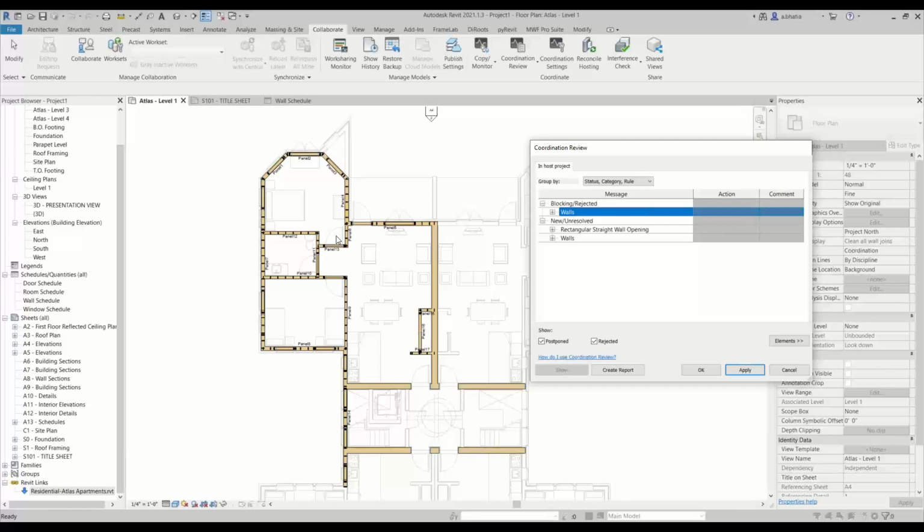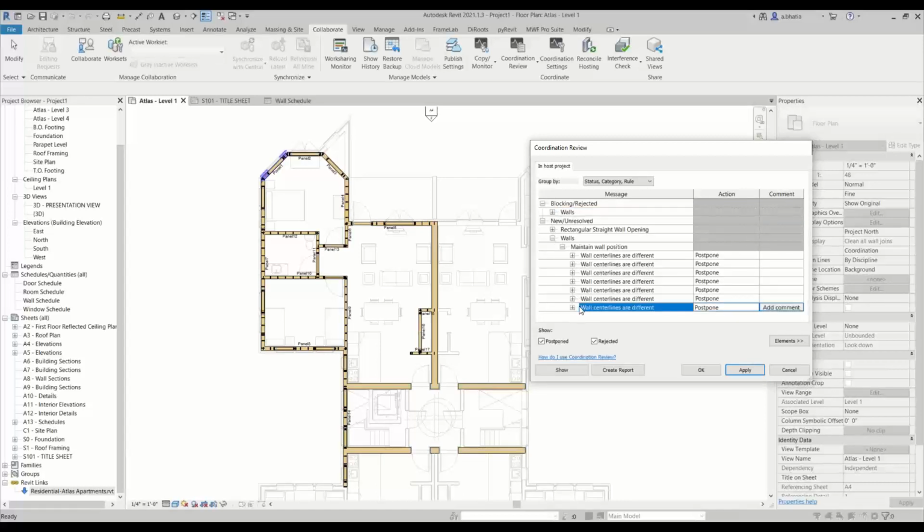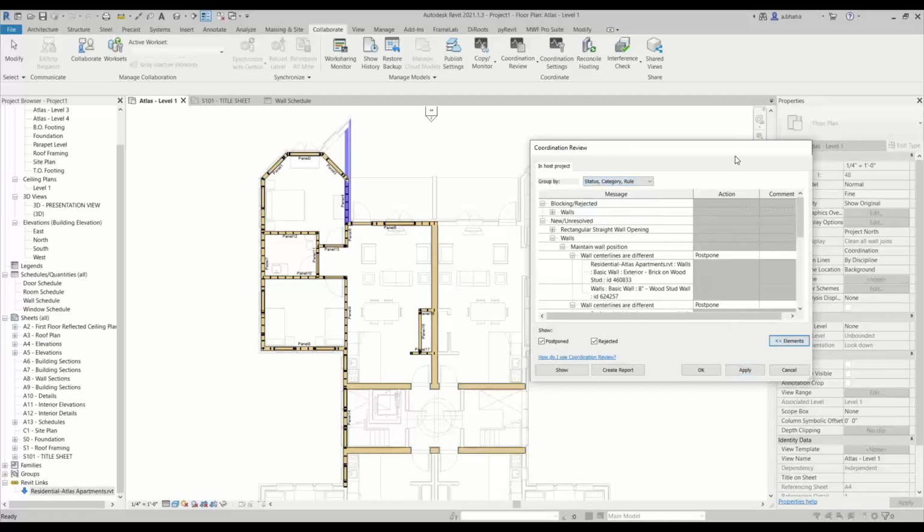So it's kind of giving you a warning, like, please go take a look if you want to. Right. So there's no way to make the framing move with the wall. You can regenerate once the wall gets adjusted. Revit will adjust the wall for you automatically if you're okay with that. And when I click on it, it tells you where it's finding this issue. Okay, it highlights it. Yeah. Nice. So you're like, okay, well, I understand it's different, so it's fine. Right. Yeah. That's basically how it works.